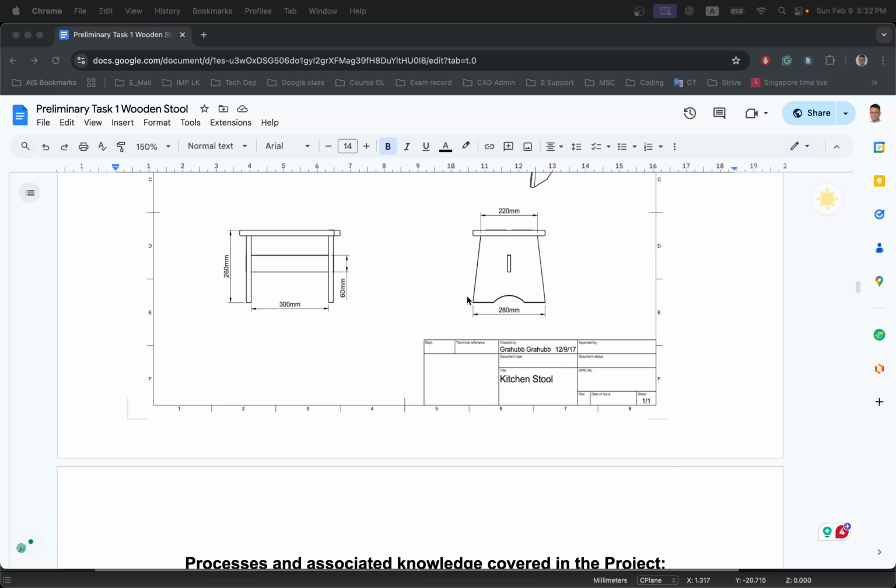To make this wireframe more visible to our human eye, I will two-finger click on the perspective and turn on the shaded mode. Once I turn on shaded mode, I will type in the height to be 19 and press the space bar. And this is our first 3D block that you have created for your kitchen stool.